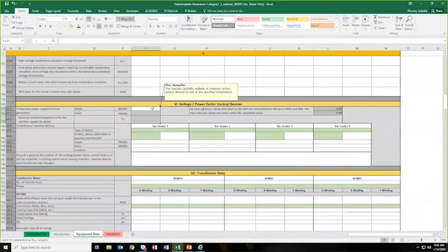The data is accessible, but that's on a different slide. The radio will tell. We call that a quality issue or performance issue, and we are going to work with the generator to see what we can do, maybe use a control scheme or have something else installed to meet all the requirements in the GIA. But the data are acceptable. So to Son's point, you can still comply with this program where you submit your actual physical characteristics, but we will identify that you have not met your power factor requirement, and we will work with you after the fact to see how we can resolve that issue.